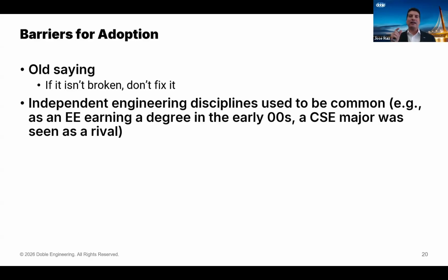I mean, one IED, intelligent electronic device, for the entire substation, many protection elements in one device, and the other vendor has taken a separate approach, which is basically virtualizing every single microprocessor-based relay in your substation in a virtual machine. So then the approach is not that different from the one that you are used to with the microprocessor-based relay, but it still is a centralized approach because it resides on one server or one piece of hardware.